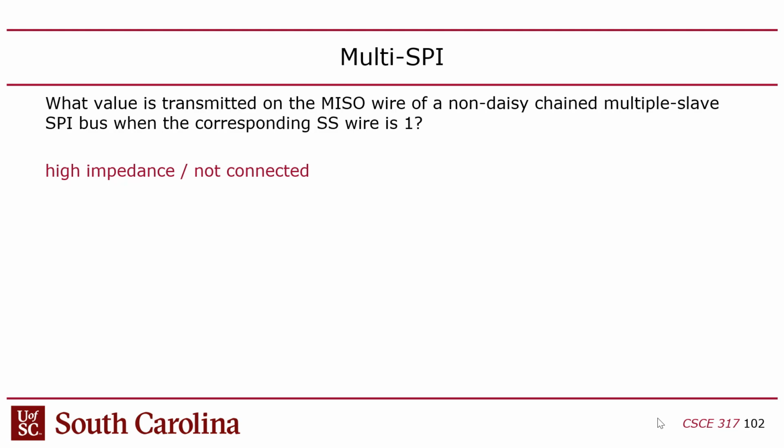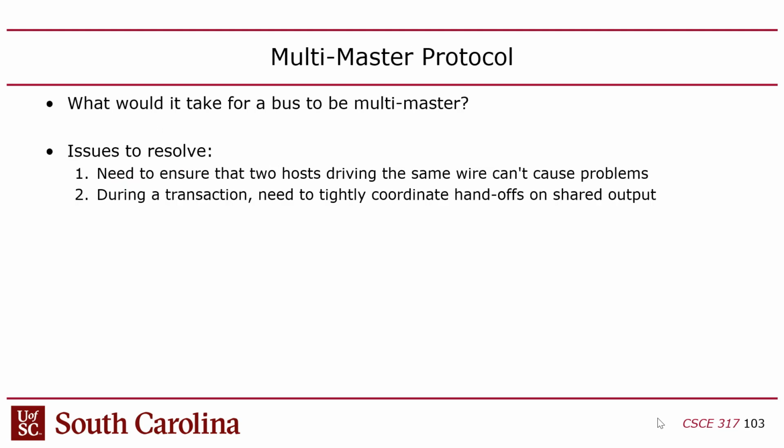You know, we've got 1 and 0, right? These are binary. But Z is like a third value now we can send. So I can send a 1 or a 0 or a Z, meaning Z means I'm not sending anything. I'm going to disengage from the bus. Okay? Now you might say, why is that important? Why do we care? Why do we have to be disengaged?